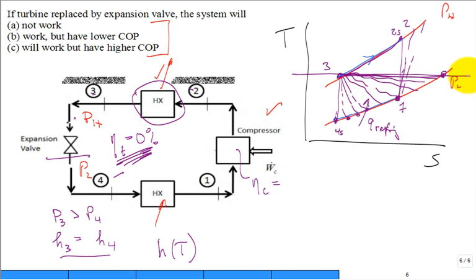Now you have some hot gas ready to go into this heat exchanger to pick up some heat. Is that going to work? Remember, we had 325 Kelvin. If you put it through an expansion valve, it's 325 Kelvin. Hold it, we started at 310 Kelvin. There's no refrigeration.